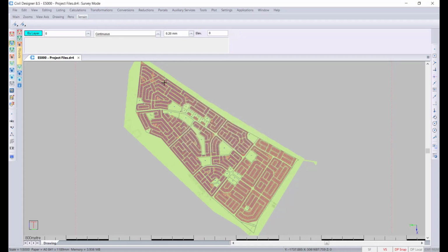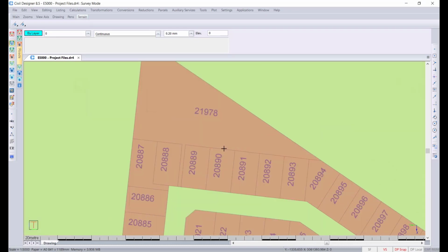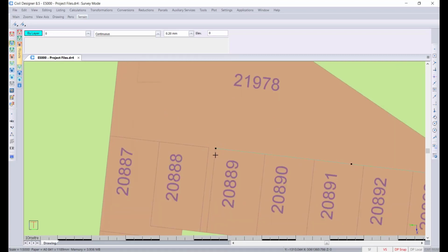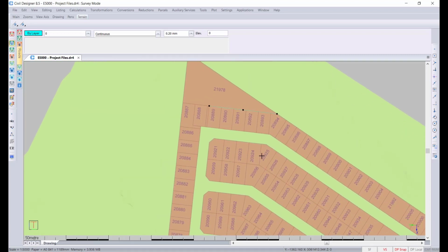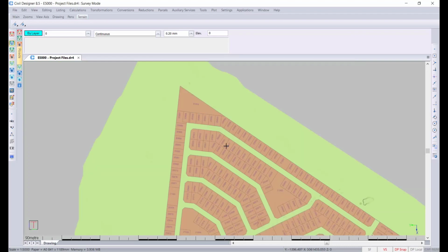It's also good to get the cadastral boundaries from the land surveyor. I sometimes found with the town planners' drawings, they often have overlapping and not neatly closed up properties, so you would get double, or you'd get bleeding into the next property when it searches for its boundaries.